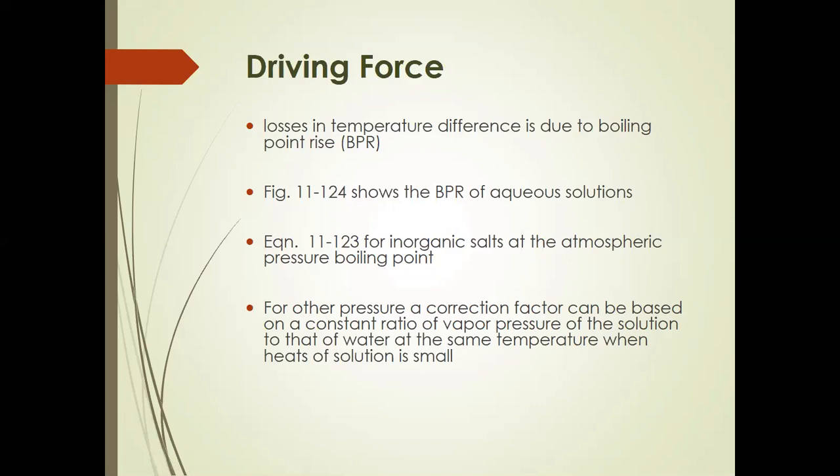So if the one that is being subtracted from the temperature of the steam is increased, then the difference between the two is decreased. So if the difference between the two is decreased, then we're saying that the driving force, the temperature gradient, was also decreased. If it is decreased, then it boils down to Q being decreased as well, and that is the rate of heat transfer being decreased.